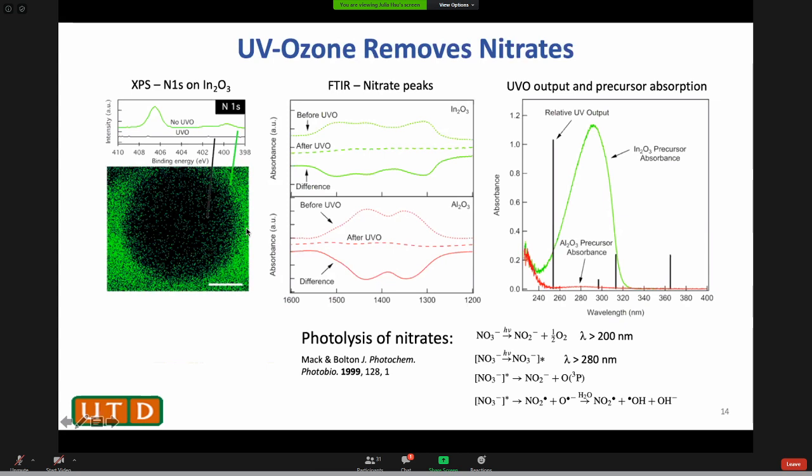I should mention the reason we don't use the combustion chemistry for the dielectric is we find that it probably makes a more porous film, because the combustion gas has to come out very quickly, and so the leakage is not as good. So for this semiconductor, we use the combustion, and the